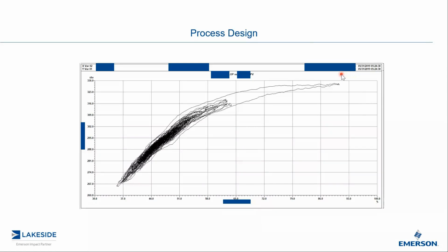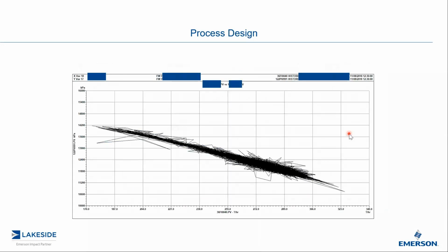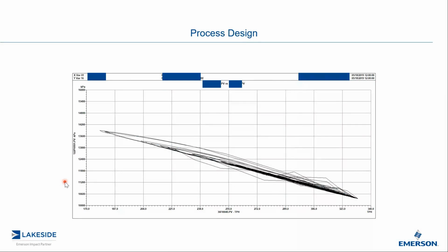So in the interim, because the pump was wearing out, I could tune it down in this part here, but it would be too slow here, and I could tune it here, but it would be unstable down here. So I needed something to compensate for this nonlinear flow curve response. Here's the pump curve. In this case, you've got the flow versus pressure, and as this was back in November, and then later on in May, you can see how the pump curve drops.